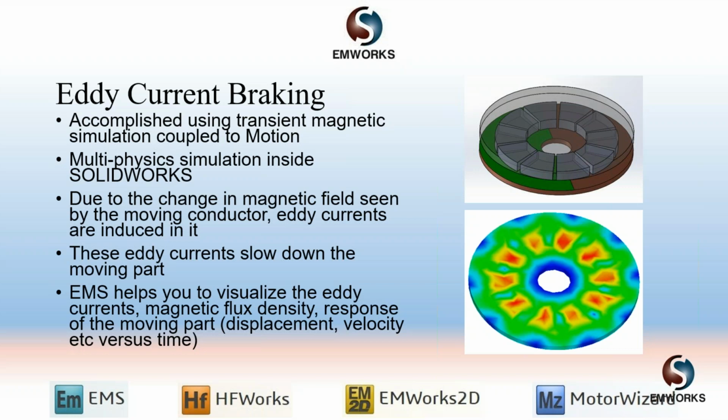If I suddenly introduce a set of magnets, as you see above, close to this disc, then eddy currents are induced in this disc, and these eddy currents are responsible for creating a retarding torque on the rotating disc, and this slows down the disc. And we will actually use this example in the demonstration.